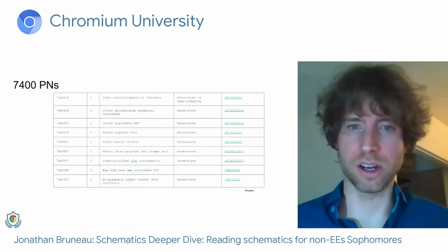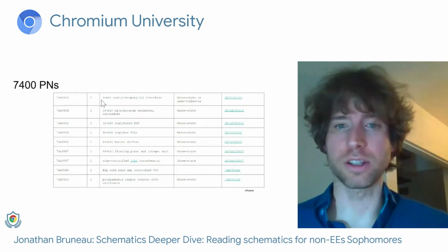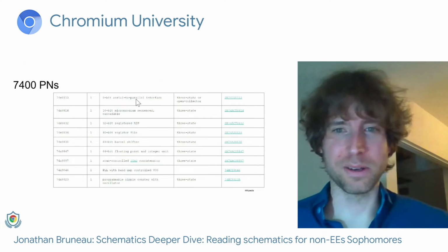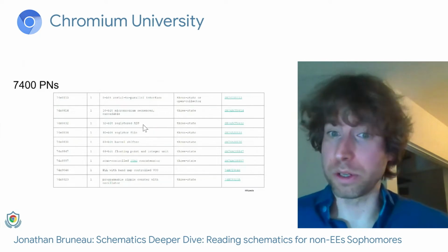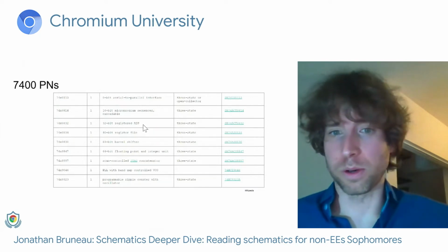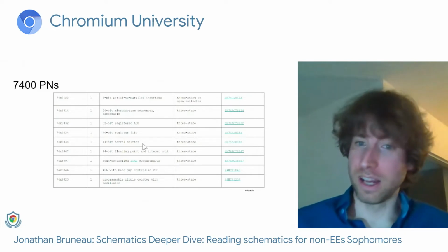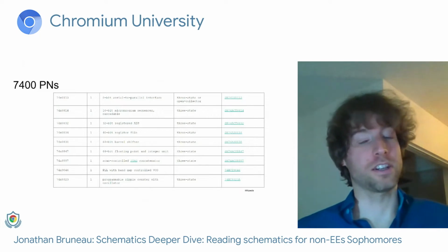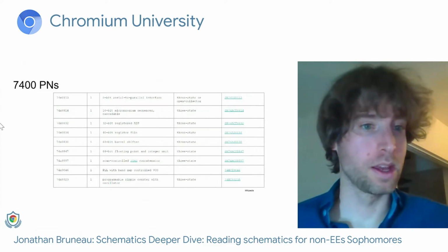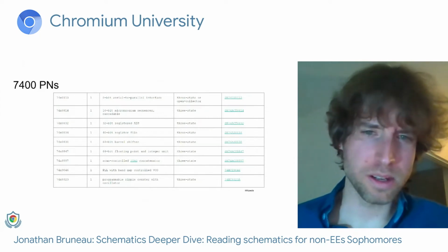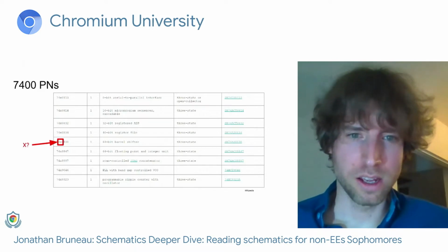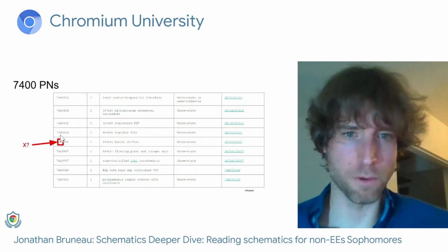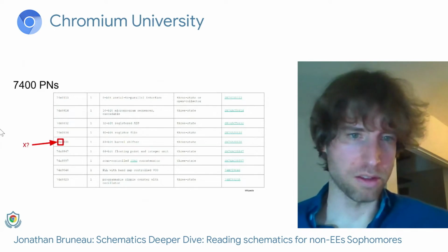And as the years went by, the 74 series kind of expanded and it went beyond simple logic and started doing a lot more complicated logic. So we have really fun part numbers like serial to parallel interfaces or 32-bit ALUs or the 64-bit barrel shifter. I particularly like this one, a JTAG concatenator. How many times have you had to concatenate your JTAGs? But something kind of interesting here is that you notice that every single one of these parts has an X here. So 74X 8838.